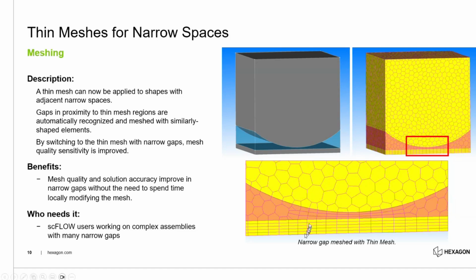But in this case, we still have large elements all the way through there. So we don't actually refine the average size, but in the thickness direction, it just generates these, apologies, talking too fast, these thinner elements, which allows us to then have significantly fewer elements in the mesh compared to having to refine this in all three directions to get that same size.